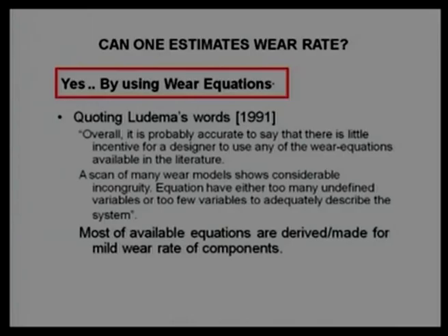Instead of that, we should always start from the root level, from scratch, and try to diagnose what the forces are, how the forces are getting transferred from one surface to the other, and whether they are intentionally transferred or are being transferred because of some system problem. A number of situations are possible. So, it is always advisable to go step by step, sequentially, and try to analyze. If we directly jump to seeing the wear and trying to find out the wear mechanism, that may not give good results.